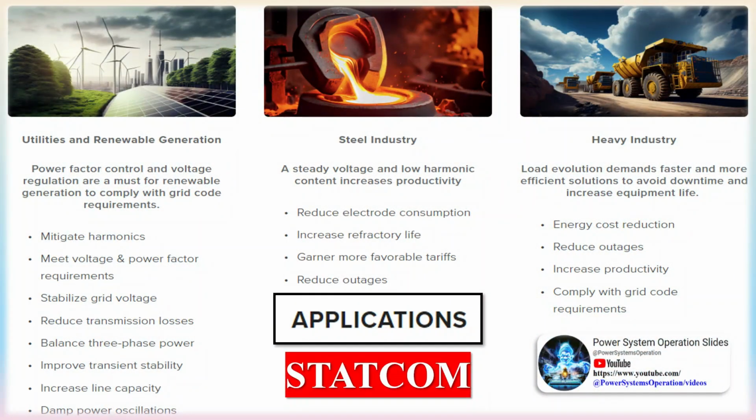Damping power oscillations with real power is more effective than using reactive power, as it does not compromise the system's voltage quality. In practical scenarios, connecting an ESS to the AC system provides better dynamic performance for damping oscillations when using a series-connected voltage source inverter static synchronous series compensator compared to a shunt-connected inverter. However, this is often impractical due to the additional costs involved.